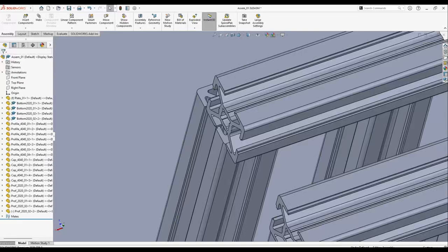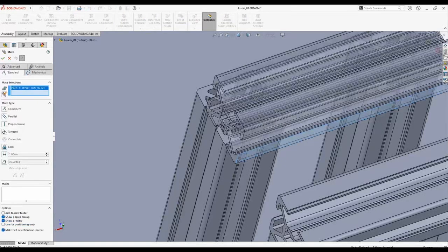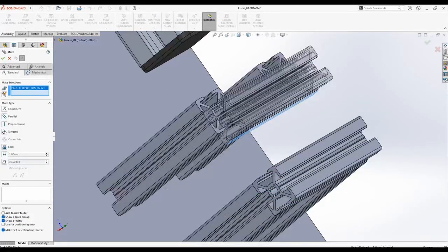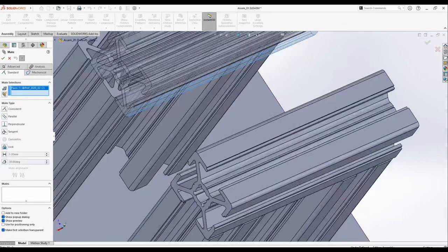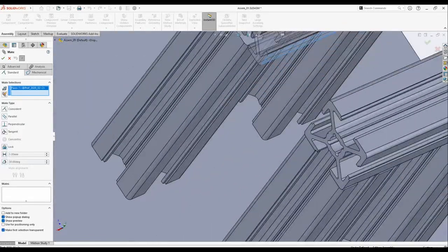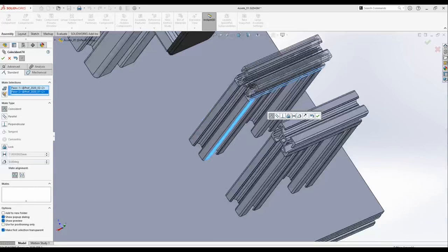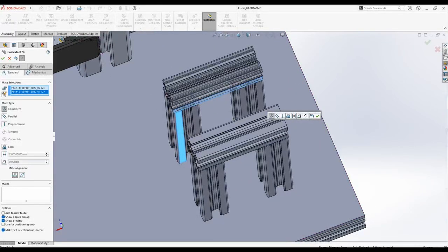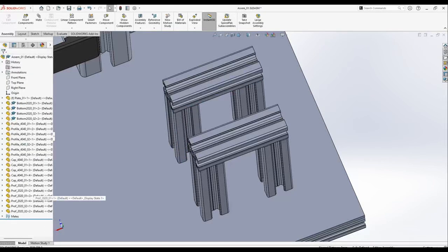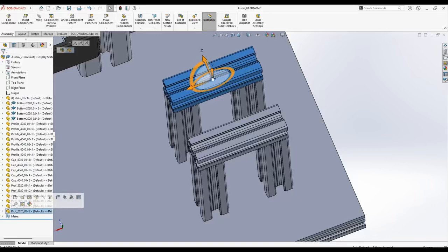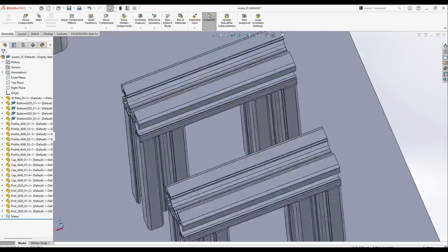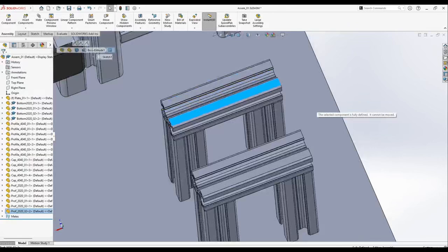Now I mate this surface, and it's better not to place the distance, while again if I need to change the distance I need to check this distance, and if I position with this surface or this surface of this part, it's the same. I always move all 3 parts with one distance only. I assign it, and I see now without the minus sign, it means fully positioned in the 3 dimensions.